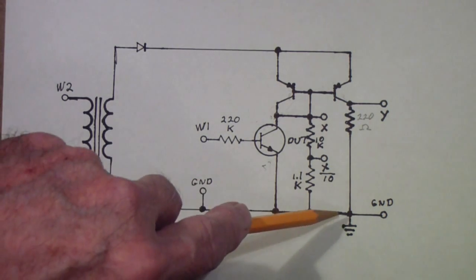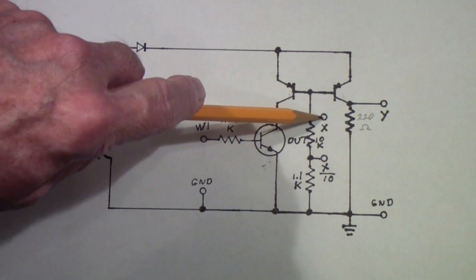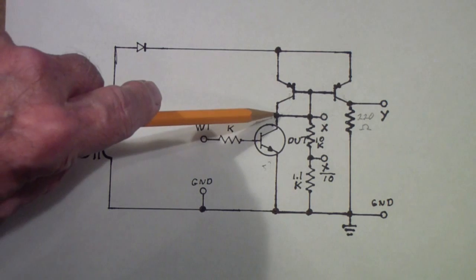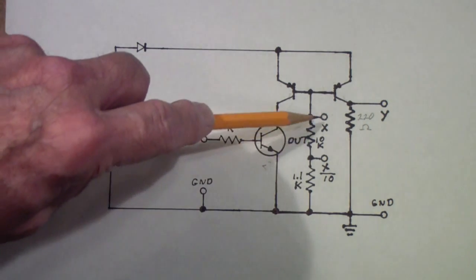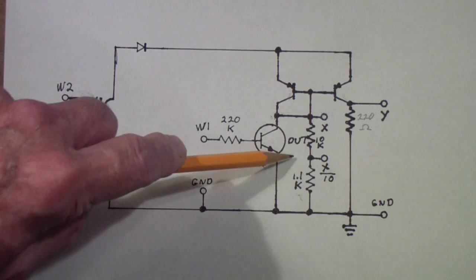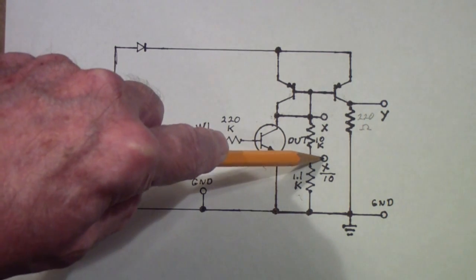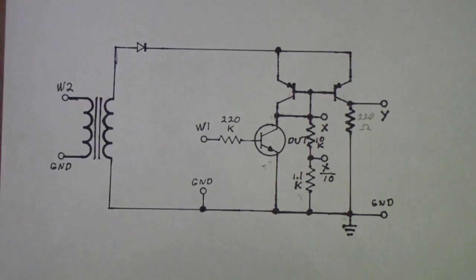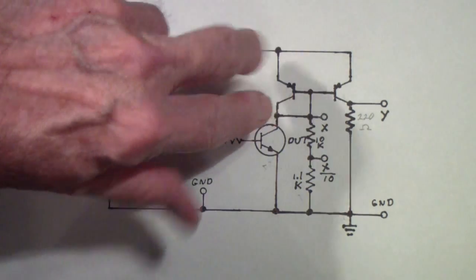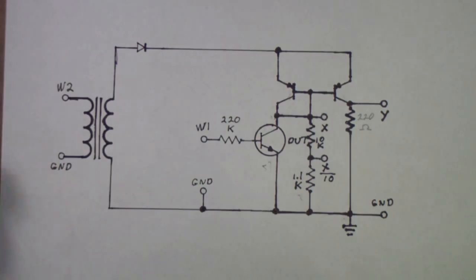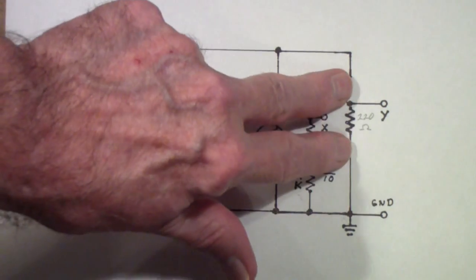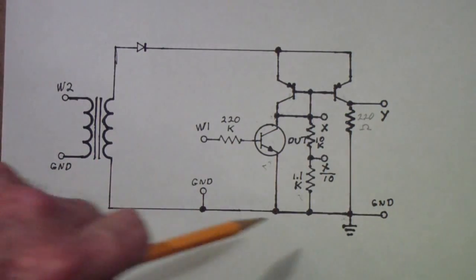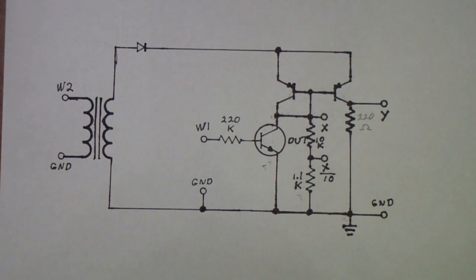So, by doing this, we can either take the voltage directly off of here, or because we're now driving this transistor above the limits of the Analog Discovery, we put a 10-to-1 divider in so we can take it here at 1/10 of the value. But the important thing is the current. Now, instead of being sensed across this resistor, which causes this point to have to float, it instead is taken across this resistor. So by mirroring the current, we're able to reference everything to ground. So we basically kill two birds with one stone.